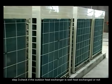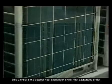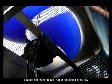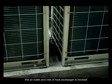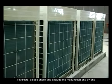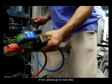Step 3. Check if the outdoor heat exchanger is well heat exchanged or not. For example, heat exchanger becomes dirty, air outlet and inlet is short circuit, outdoor fan motor doesn't run, or fan speed is too low, the air outlet and inlet of heat exchanger is blocked, the distance between outdoor units is too short, and so on. If it exists, please check and exclude the malfunction one by one. If not, please go to next step.